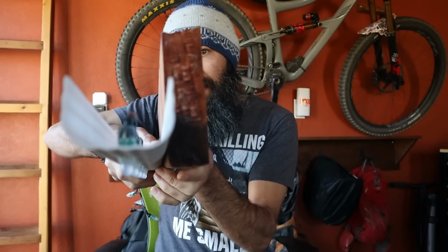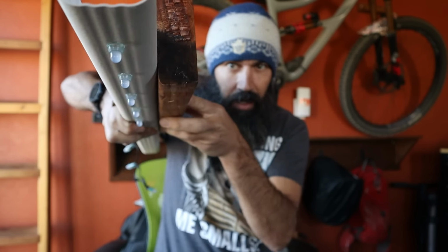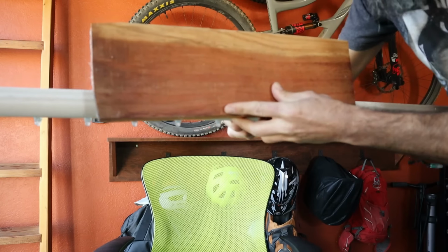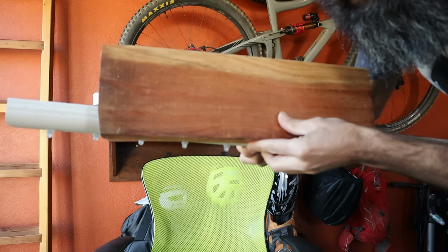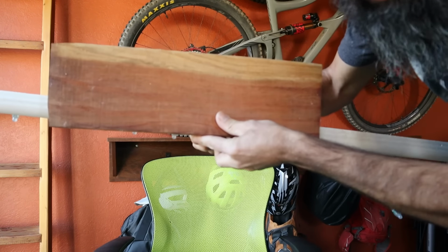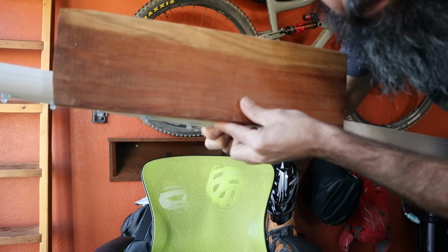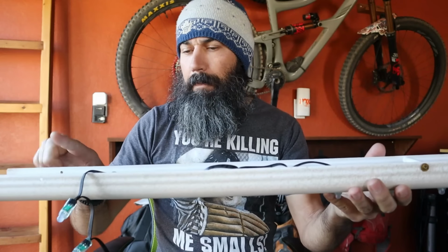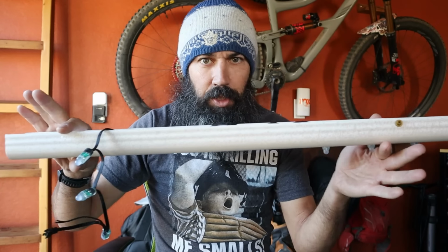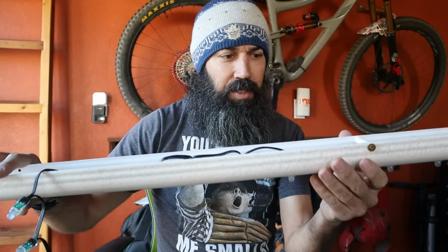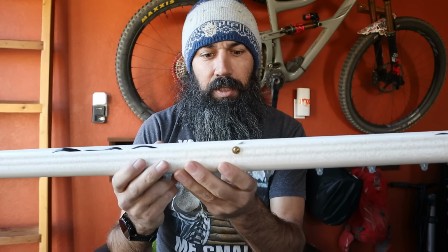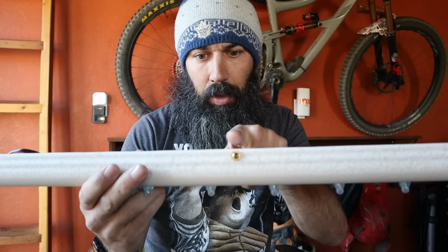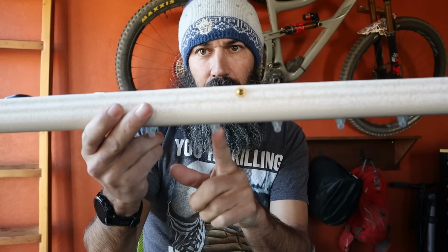So that that's just about even with the bottom of the fascia, but that the LEDs, if we were going to look from the front of the fascia, the LEDs should stick down just past so that they're just visible. Okay? So that's ultimately the install process. I mounted about every 18 to 20 inches or so. You could get away with about every 2 feet. The thing that I was careful to do was to make sure that any mounting hole that I drilled across was not directly in line with one of the pixels, right?